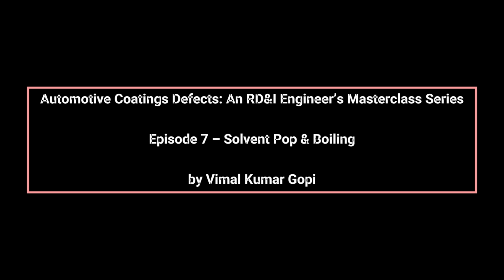Additives play a supporting but limited role. Defoamers and air release additives can help collapse entrained air bubbles introduced during mixing or application, but they cannot relieve solvent vapor pressure once skinning has occurred. Flow and leveling additives do not prevent solvent pop and should not be relied upon as corrective tools. In some cases, incorrect additive selection can worsen the problem by accelerating surface closure or reducing surface elasticity.